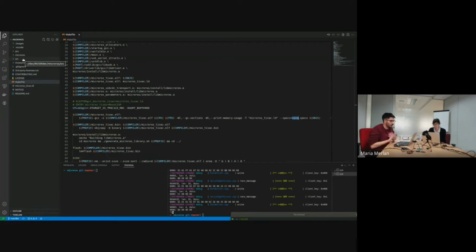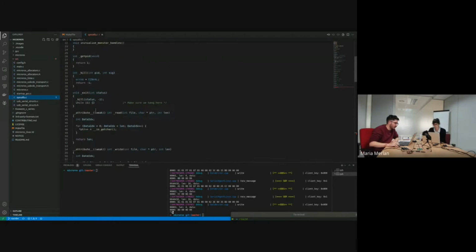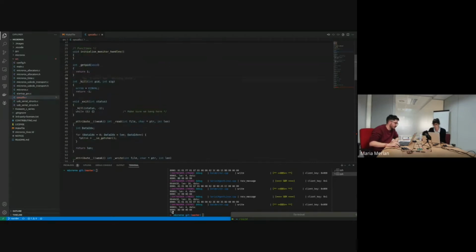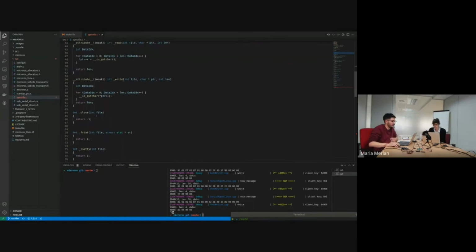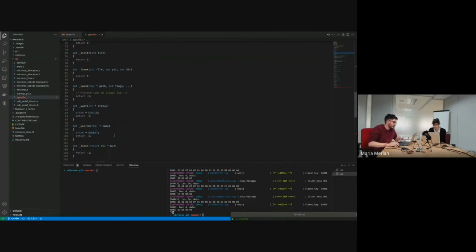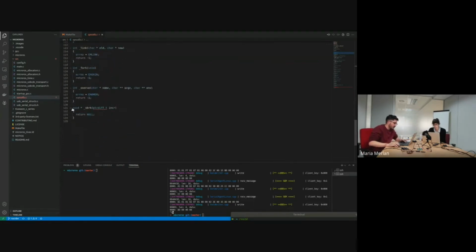So, for example, we are going to handle the micro-ROS dynamic memory using a custom allocator that I'm going to show later. As you can see here, for example, we are implementing all the syscalls, just returning errors because we don't have support for the complete libc. In fact, the most important one is this one, the sbrk, which shows that this system does not have any kind of dynamic memory approach using the system heap at linker stage. That means that we cannot use malloc.